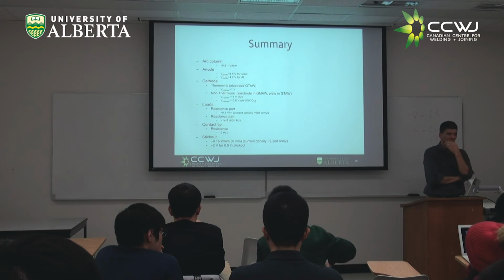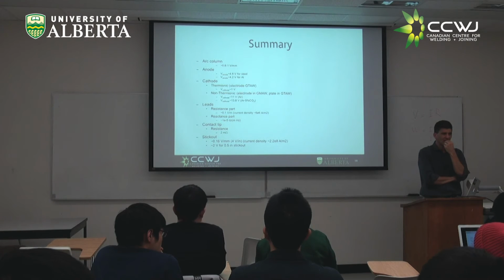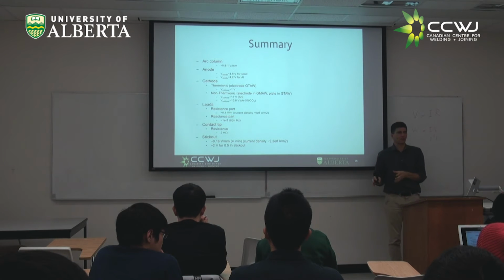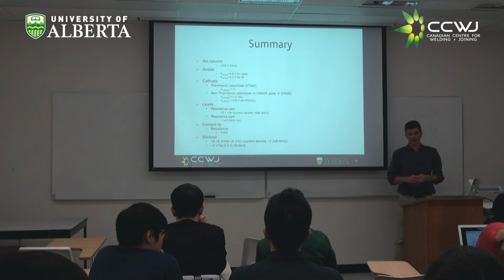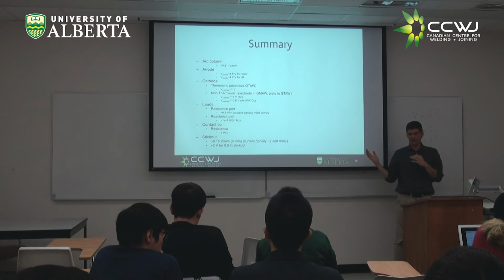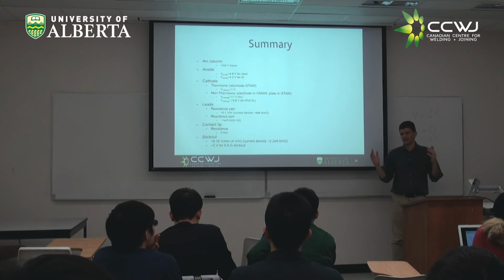The problem with these types of machines is when you have a lot of inductance in any industry, you will have to correct your power factor. All these types of problems will arise when you have that. What you say is that very often when you have electric motors and many types of operations, your factory ends up acting as a big inductance, and that's a problem. You get charged for that, and there are many problems with that. So companies often have a big bank of capacitors to offset it.